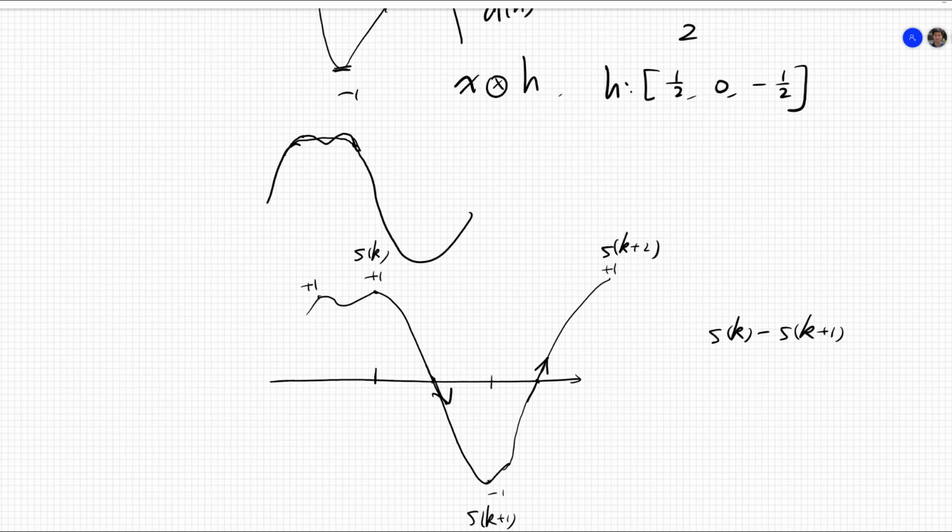If this difference is positive, I have a falling curve. Using that, I can tell the difference between these two cases and use that in building my timing detection output. Now, why do we need that? Because these two cases tell me whether my offset tau should be positive or negative. I need two non-zero values around 0 that give me a very clear positive or negative direction.